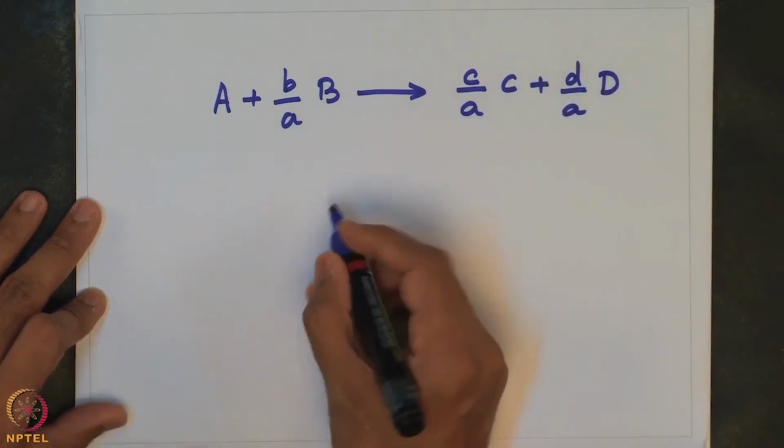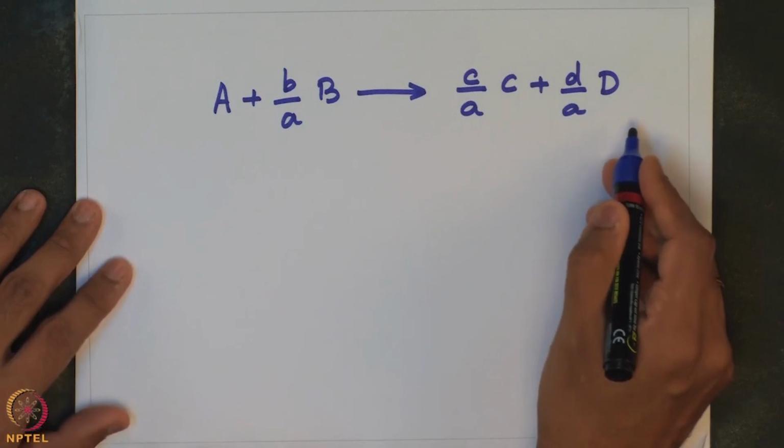that is the stoichiometric equation that we actually used for designing this particular packed bed reactor design. And so, to summarize, what we have seen in this class is we looked at the packed bed design, we made some simplifying assumptions, and we found out the relationship between the length of the reactor and the potential conversion that could be achieved at the product stream. In the next class, we will look at what are the effects that would control the design of a packed bed reactor that we have considered in this lecture.